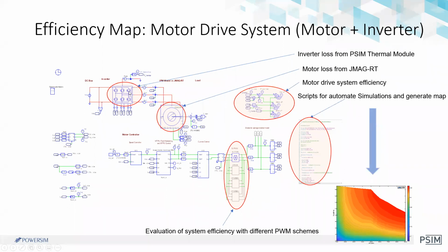So we have added the losses happening here in the inverter, that is switching and conduction losses. So we have a thermal module for that. We will also show that we can see which switch, which IGBT or silicon carbide MOSFET we are using here, and all those things. Also we are using, let's say, a space vector PWM here for this case. You can have a different DPWM, DPWM 1, 2, min max, different schemes, whatever. It's totally editable. You can also have a multi-level inverter, if you want to have some multi-level inverter there, and you can easily change the control scheme here, right?